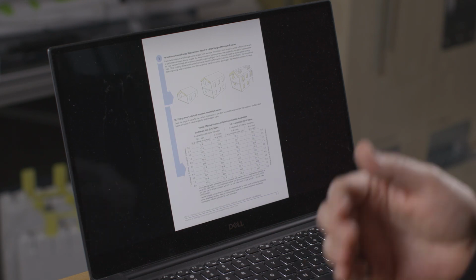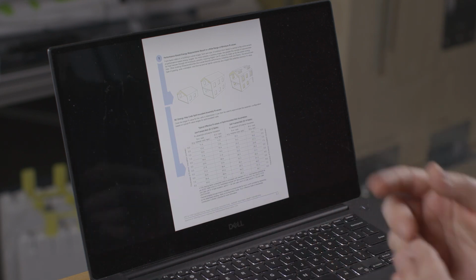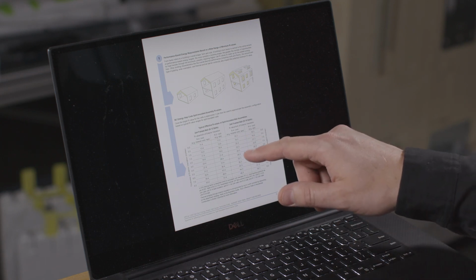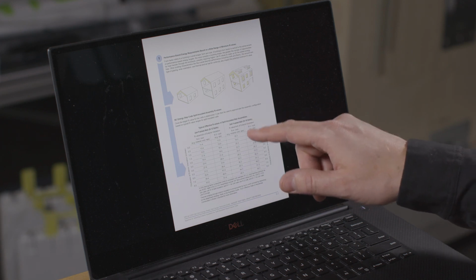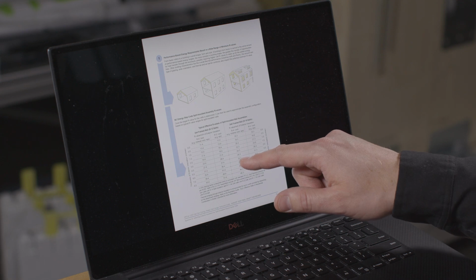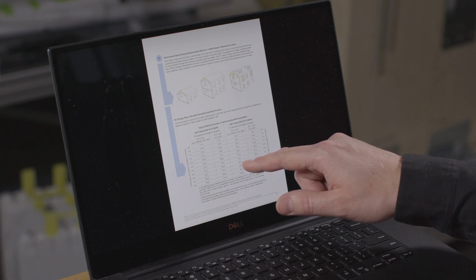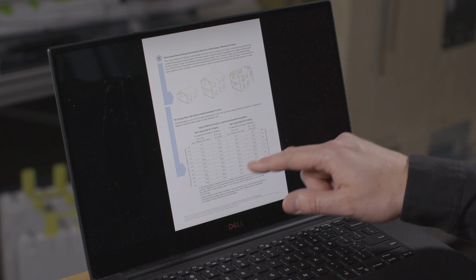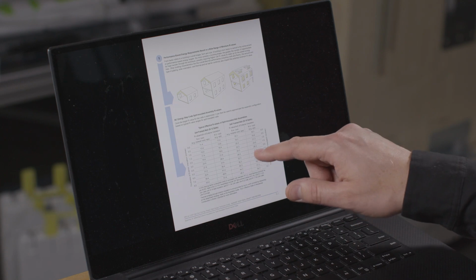Okay, so then you're going to go in and you're going to look and say, okay, with that R35 wall, I've got a number of different ways of doing this. I want to use R4 per inch or R5 per inch exterior insulation with batt framing. I'm going to need roughly, let's say 5 inches to get to R36, or 5 inches of mineral wool or EPS, or 4 inches of XPS. So you can sort of see in the table there, that would be your target. So you use this table to figure out the target, figure out the thickness of exterior insulation.